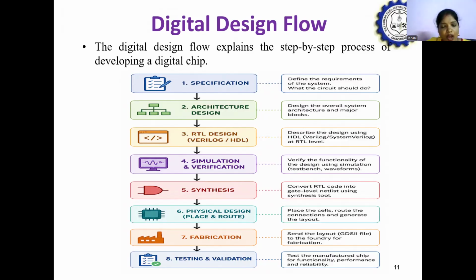components. After the physical design, the complete design is given to fabrication. That means the complete design is sent to the manufacturing plant. In this manufacturing plant, we are going to send the layout in the form of a GDSII file to the fabrication. Here they are going to use the semiconductor fabrication technology to make the final chip.